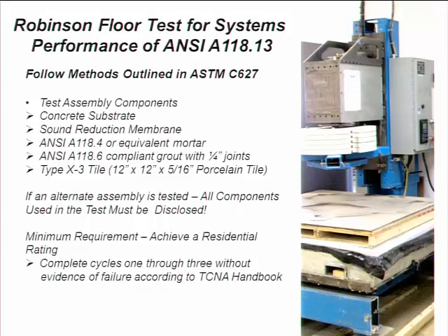But what I want to convey is there are a lot of different avenues when you're looking at a soundproofing membrane. It's not just the soundproofing, it's the performance of the entire system in reference to its bond, as well as whether it can be used in a residential installation or whether it can be used in a commercial installation. And that's the purpose of the Robinson test panel being incorporated into this testing system, because you want to define at what level of performance your membrane is capable.